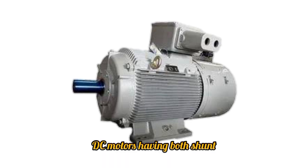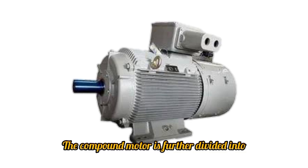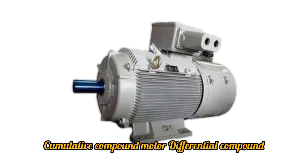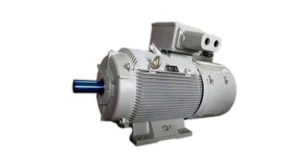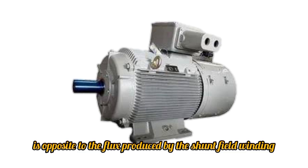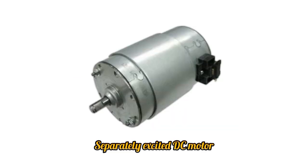Compound wound DC motor. DC motors having both shunt and series field winding are known as compound DC motors. The compound motor is further divided into cumulative compound motor and differential compound motor. In a cumulative compound motor, the magnetic flux produced by both the windings is in the same direction. In a differential compound motor, the flux produced by the series field windings is opposite to the flux produced by the shunt field winding.